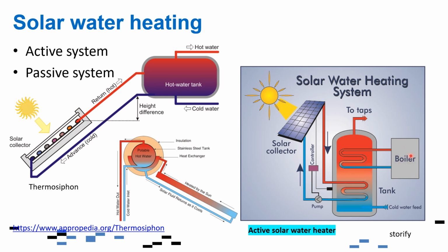As you can see, there's an extra boiler, or a backup boiler, to heat up the water if you don't have any solar radiation, for example at nighttime. So this heated water will now be used towards the tap. The liquid here, the cold one, is just recirculating. Once it goes back towards the tank, cold water coming from the mains is supplied over here. So it acts like a heat exchanger, exchanging heat and heating up the cold water.